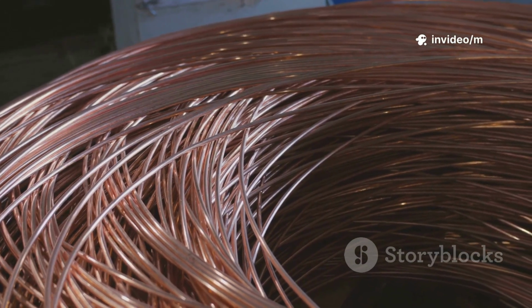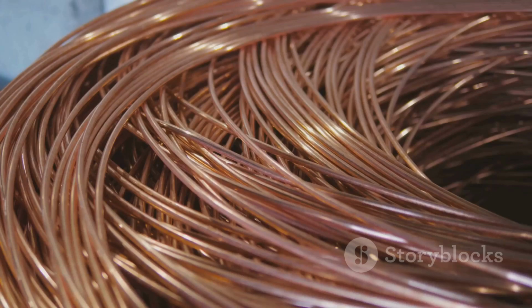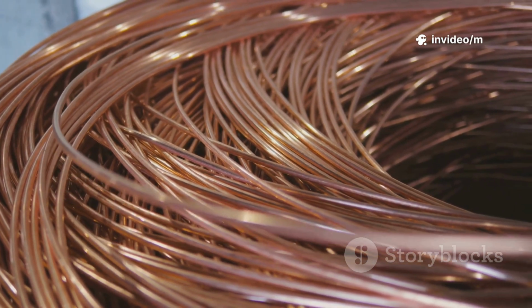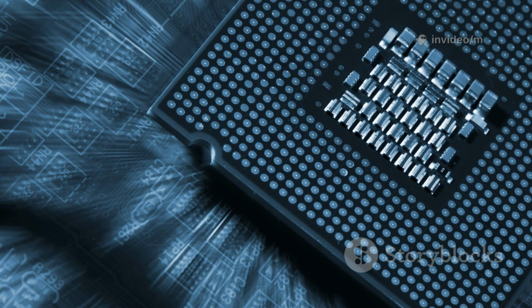Resistivity is how much a material fights electric current. In metals, heat makes atoms jiggle and vibrate. Those vibrations scatter electrons, increasing resistivity. So wires get worse at conducting as they warm. In semiconductors, more heat frees charge carriers. That lowers resistivity, up to a point.